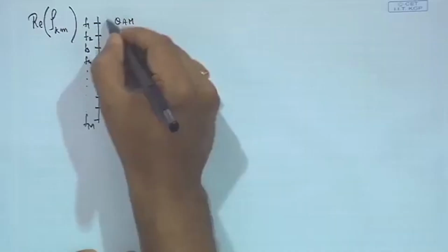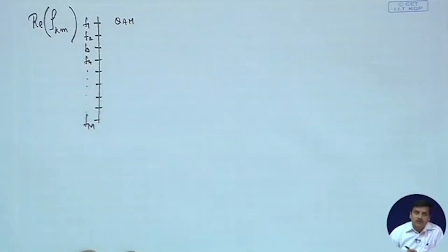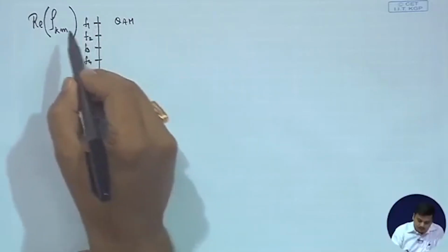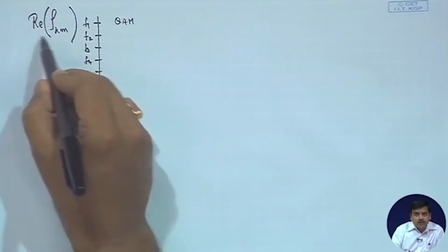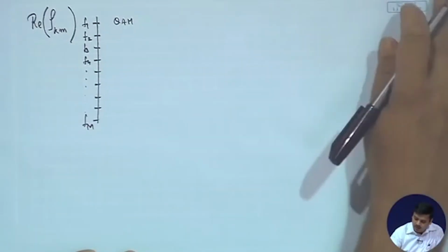So, the other direction you can go towards is not only to choose, but also to send more bits on a particular chosen stream. If QAM has k2 bits and the selection requires k1 bits, together you can have k1 plus k2 bits communicated, not only by selection, but also by further modulation. Since we are talking about QAM-like signals, you cannot just use the real part of rho km,